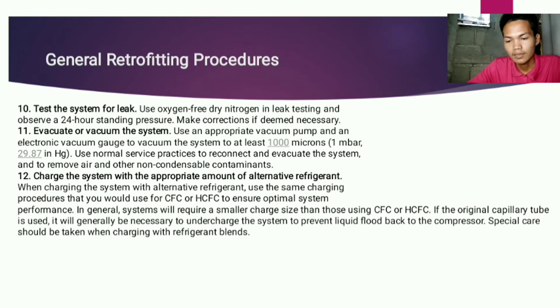In general, the system will require a smaller charge size than those using CFC or HCFC. If the original capillary tube is used, it will generally be necessary to undercharge the system to prevent liquid flood back to the compressor.